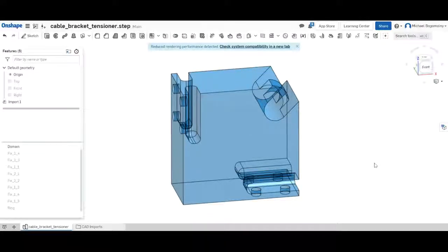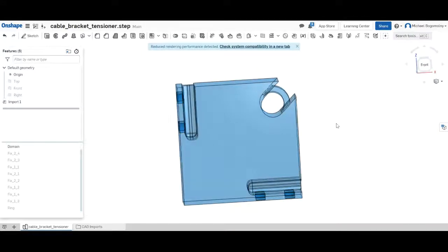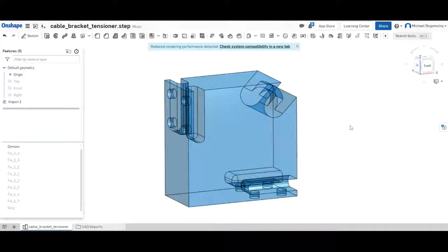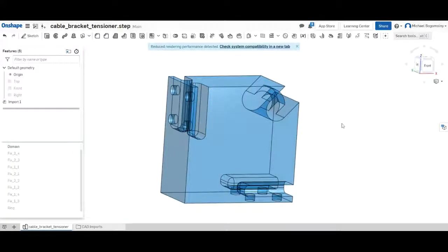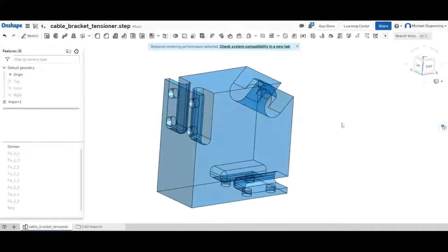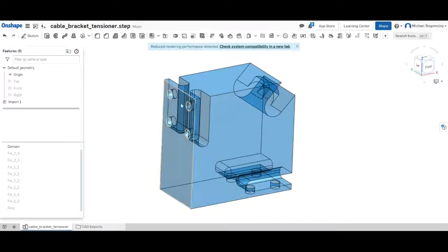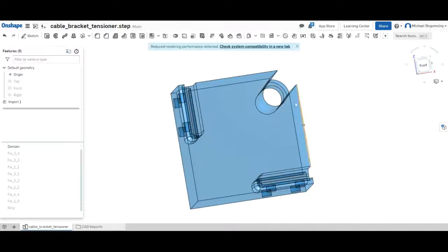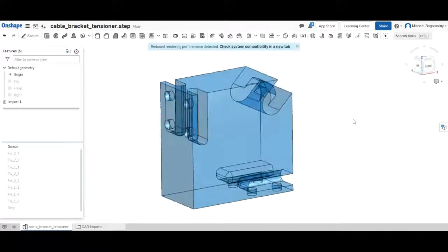So the first step is to create an initial design space of our model. The initial design space should include the biggest possible available volume. Now, while creating this model, as you can see, the part should fit the assembly, and some areas around the bolting areas and ring here should be kept untouched by the algorithms.